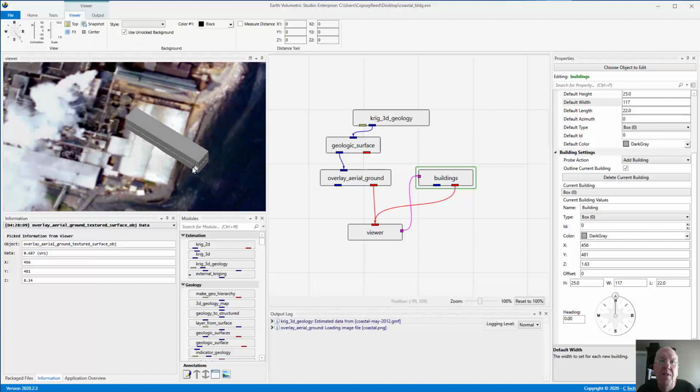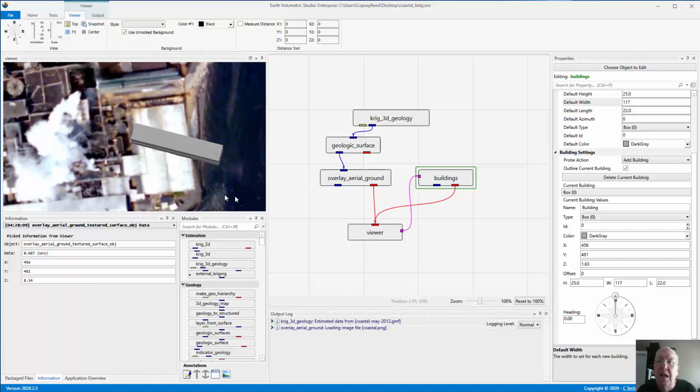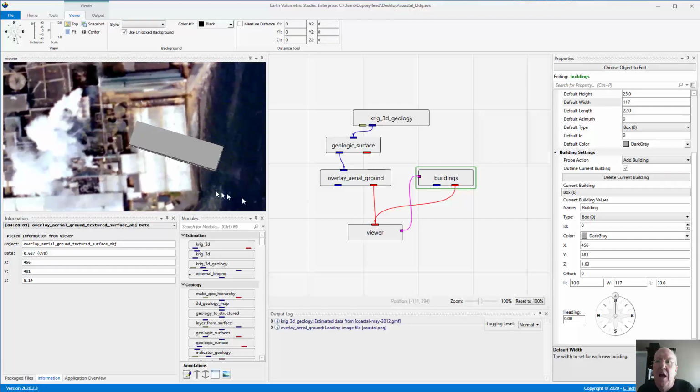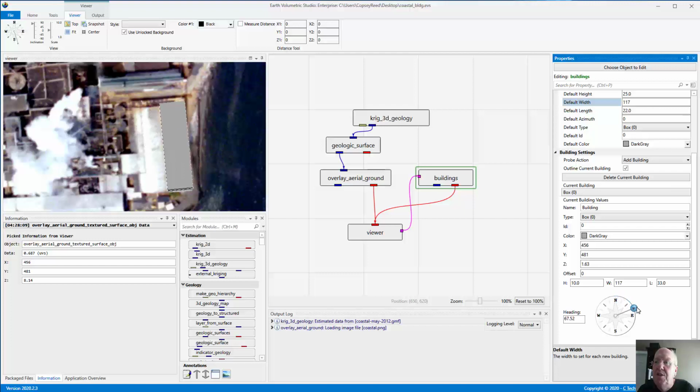And we need to orient this building, and we can do it manually, and we'll do that in a second. I didn't measure the length in this direction, but from memory, just to save some time, I'll tell you the length is about 33. And we want this building to be about 10 high. Everything here is in meters. So at this point, I want to rotate this building. And when I grab this wheel, it's very hard to get super accurate because of just the position.